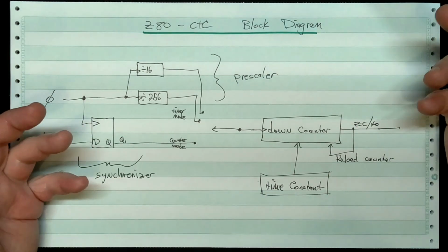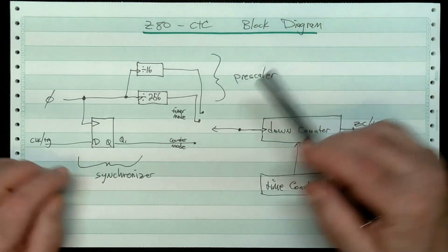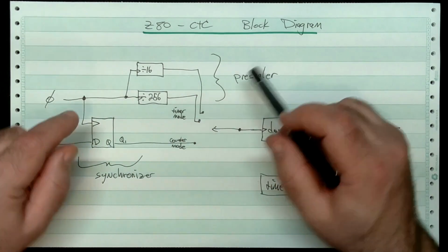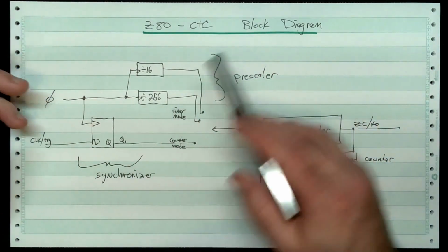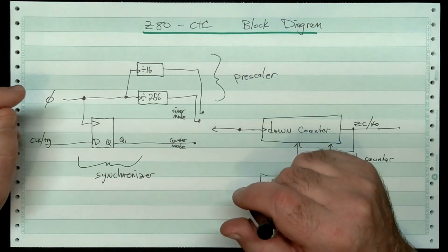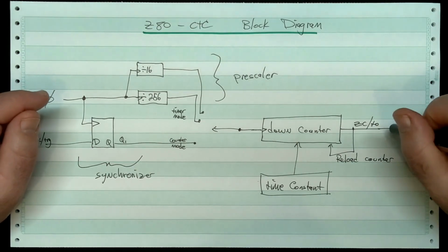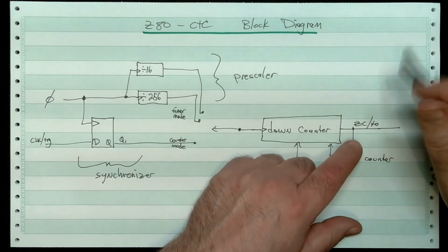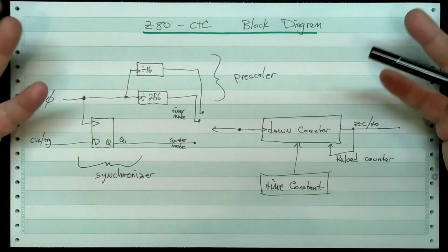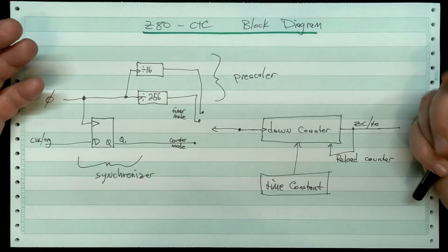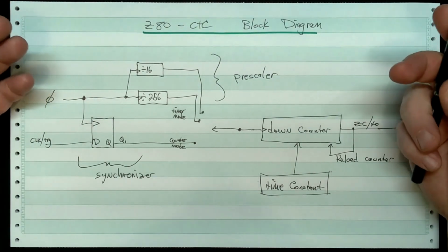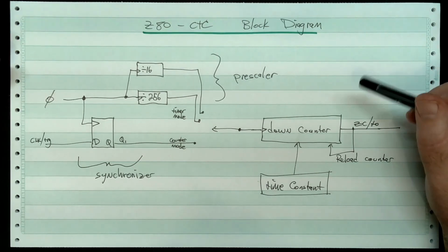So that's great, all right? Why would you want to use this instead of that? It depends on your application. In our application, for example, we need to generate the bit rate for the SIO. And we want to run the SIO at standard bit rates, like 56 KB or 9600 bits per second and stuff like that.